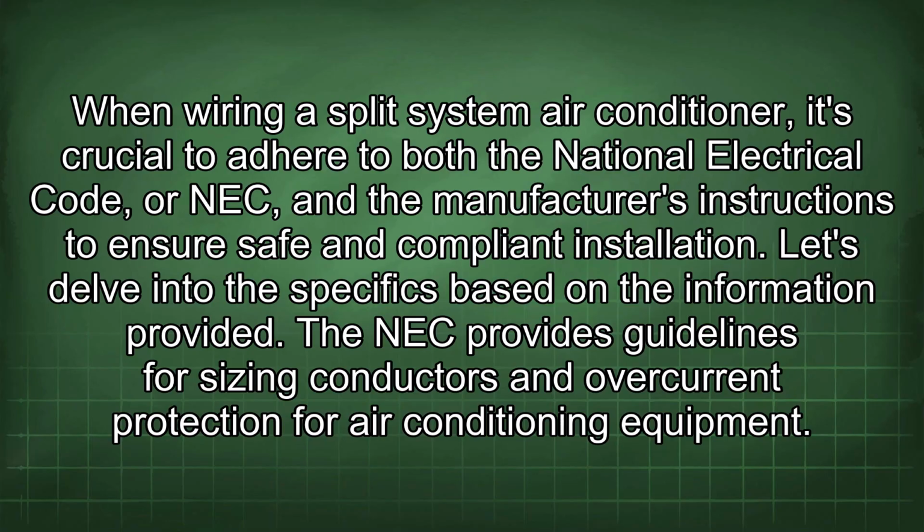When wiring a split-system air conditioner, it's crucial to adhere to both the National Electrical Code, or NEC, and the manufacturer's instructions to ensure safe and compliant installation. Let's delve into the specifics based on the information provided. The NEC provides guidelines for sizing conductors and overcurrent protection for air conditioning equipment.